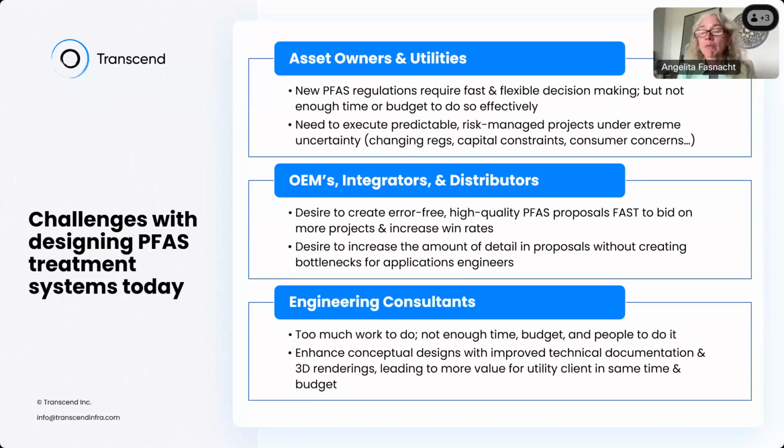So for those of you, probably everybody knows the rule, but the EPA set maximum contaminant levels, MCLs, for PFAS: PFOA and PFOS at 4 parts per trillion. We do have another hazard index approach also for other PFAS: PFHxS, PFNA, PFBS, GenX, and so on. So basically, the rule gives water systems up to 3 years to comply. By 2027, EPA's new regulation will be fully enforceable as of public notification requirements. And 2029 is when we have to complete all remediation for drinking water, offering a stronger protection at utilities.